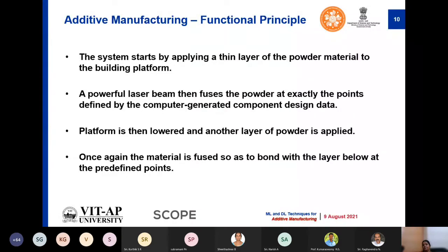You know there are two ways in which you can do additive manufacturing. One is that your platform is stable and your printer head is moving, and the other is that the printer head stays in place and the platform moves, right? You have a lot of variants. You can try small things and make some changes. Nowadays, you have good options to rework or remodel your 3D printing machines also. That's also what we are trying to do, right? We can remodel the machine, the way in which it works.